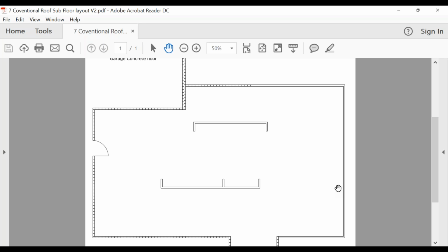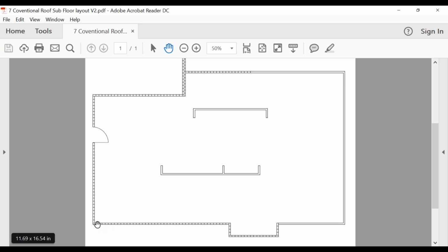If you want to draw this, I'll wait until you've got it drawn so I don't go too fast for you. Yeah, I'm following you. That's fine, Adam. Then I've drawn one here, the length of this wall, all the way through. Without knowing the exact measurements, in reality you probably could not have to put it through there if you didn't want to, but I just put mine all the way through. And then I've done one in this little part here as well, parallel with that brickwork, in with my 25 mil for the cavity, because I just know that's where they have to go. I've obviously got to have one on the outside.